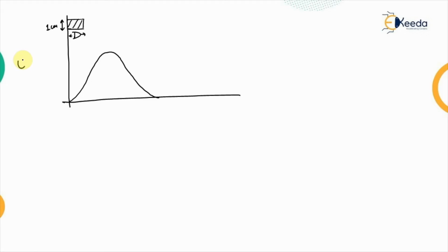Again 0 values. This is the plot of discharge versus time. Then another rainfall has occurred, again for the D hour. So this value is also D, and the depth of the rainfall will be 1 centimeter. It will start after D time, because once the first rainfall has completed, the second one will start. Then the third rainfall has occurred, again of D hour duration, so that will again start at the lag of D hours.